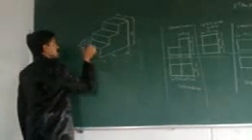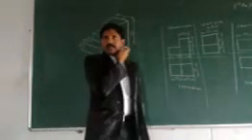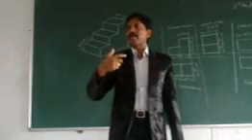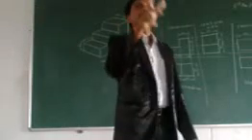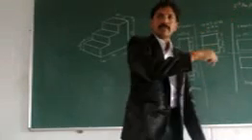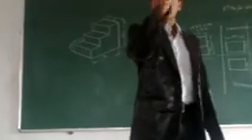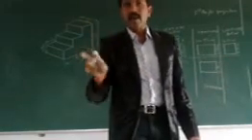And next come to the length. So this is 30 and 30 and 30. So in the final examination also, there are breakup dimensions given on the object. So that means we imagine ourselves which split dimension is suitable for the total dimension. So if there is a 90 and there are 3 splits, we divide into 30, 30, 30 like that. Similarly, there is a 45 dimension, so 15, 15, 15 like that. If there are only 2 steps and there is a 60 dimension, we divide into 30 and 30. If an individual dimension is given, you have to select the individual dimension. If it is not like that, we divide into equal spaces.